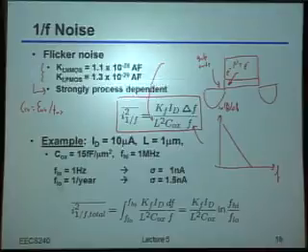Yeah, capacitance goes up. So if I've got one electron jumping in and out of a larger capacitor, how much voltage change gets induced due to that effect? Or rather, does it get a larger voltage change or a smaller voltage change if you increase the capacitance? Yeah, it's a smaller voltage change.